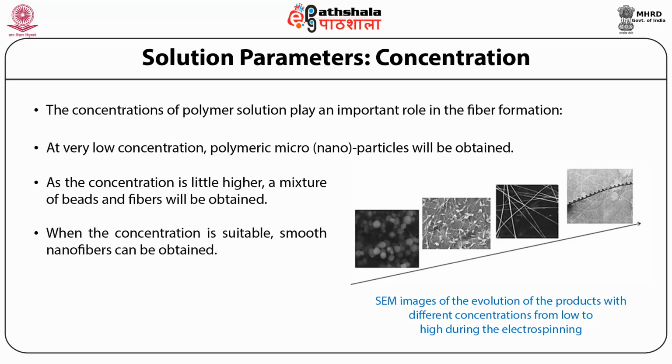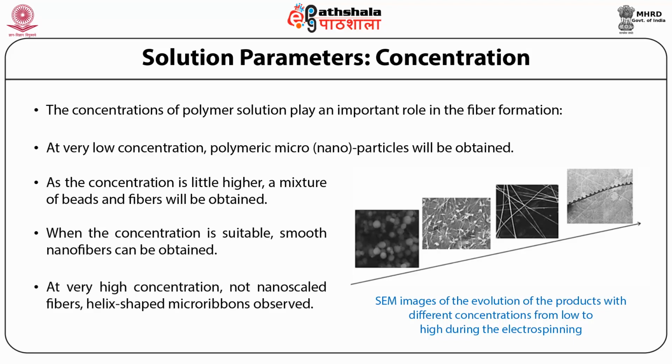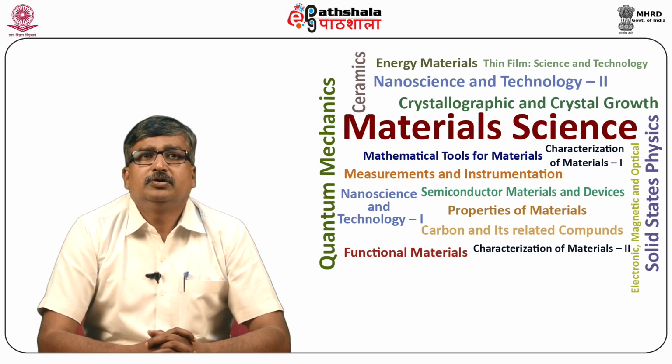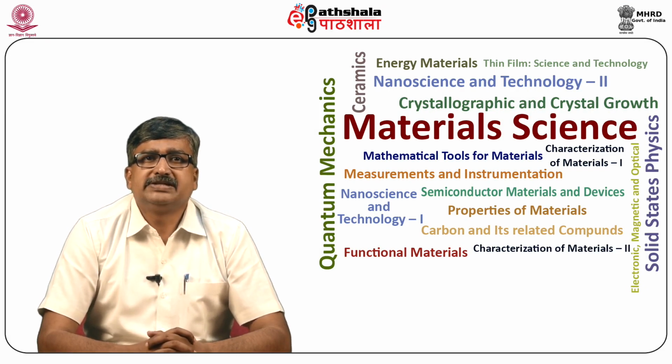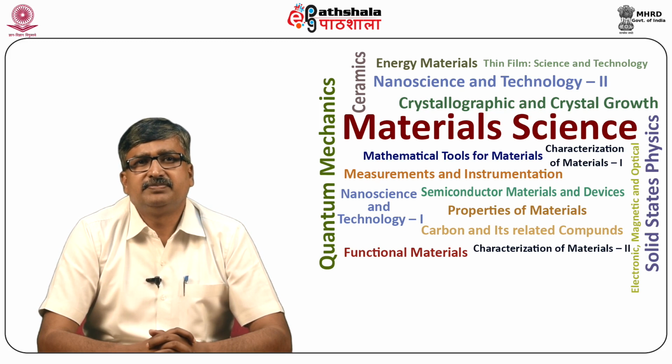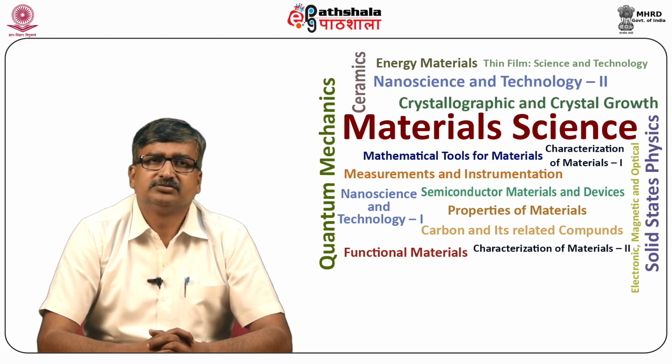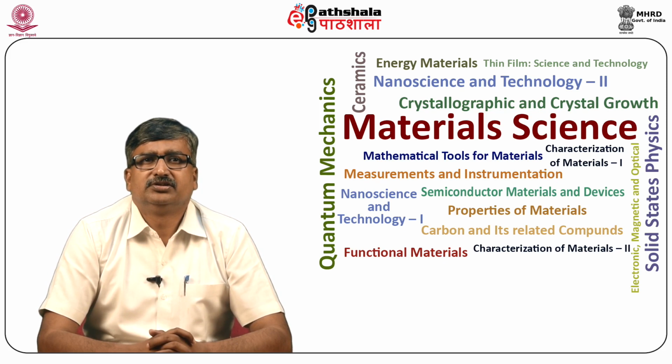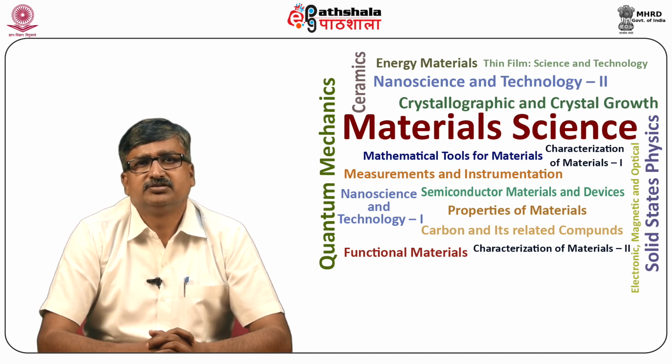And the fourth and final, if the concentration is very high, non-nanoscale fiber, helix-shaped micro ribbons will be observed. So, the solution parameters, especially viscosity, is another solution parameter which one needs to understand carefully and optimize depending on the solution. Solution viscosity is the critical key in determining the fiber morphology.